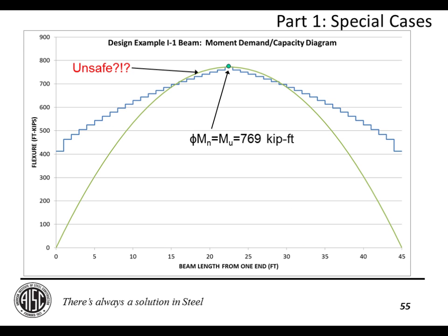One thing I'd like to point out is when you design a beam right to its capacity. So let's say you're a very progressive designer and you end up with a moment capacity and demand equal, you end up with this teeny little zone that this method of sectional cuts would call unsafe. And that's not true. Again, we're just not that good. Safety factors, assumptions, etc. are enough that you can ignore that tiny little issue with this particular method.